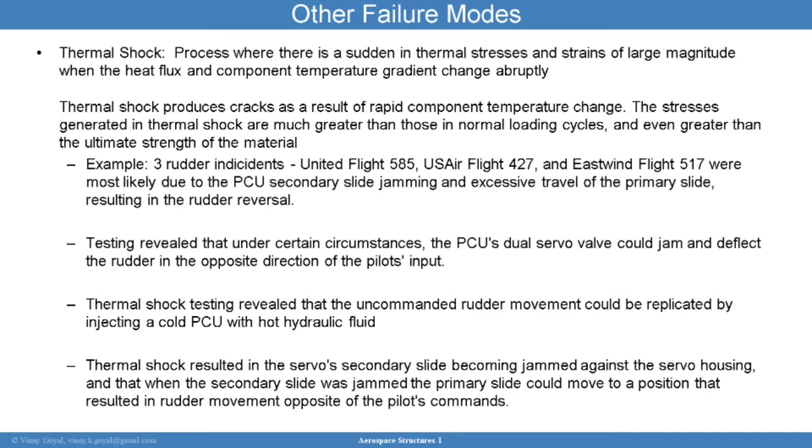And that when the secondary slide was jammed, the primary slide would then move into a position that resulted in a rudder movement opposite of the pilot's command. So that's an example of thermal shock environments that can cause structural and functional performance issues in the system.